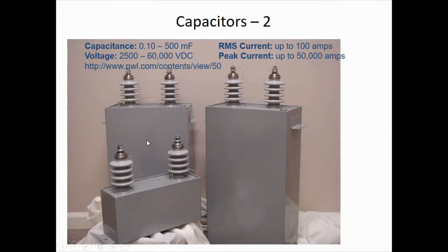If they are small, what will happen is that a capacitor, of course, is two metal plates separated by a dielectric, and at such large voltages, the dielectric would simply break down and become a short circuit, unless it is made thick enough to withstand very large voltages.